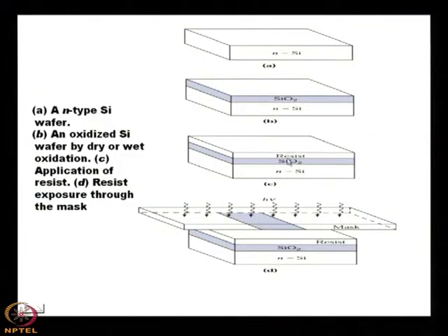The mask can be positive, the mask can be negative, different kinds of situations can be there. Then you put that mask on the photoresist coated sample. Here you see that this is the mask. In this mask you see that at the mid portion there is some window type of thing. Then when ultraviolet light is incident on the mask, what happens?